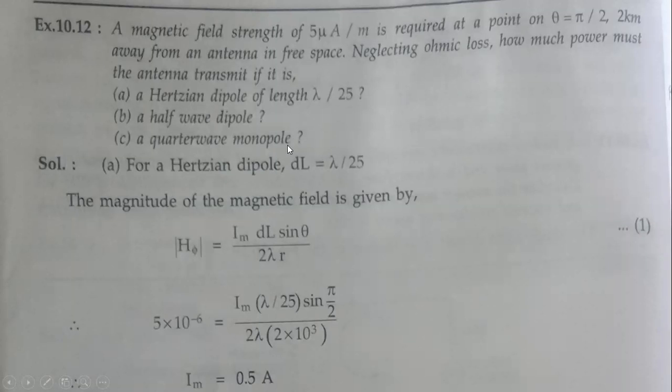So how can we start? The A part is for the Hertzian dipole, so dl is equal to lambda by 25. The magnitude of the magnetic field is given at the beginning of the question, that is 5 micro ampere per meter. As theta is given, the possibility is either the cylindrical or spherical coordinate system. You can take the spherical one, just looking at the shape of the transmitting antenna in the dipole form. So here the magnitude of that magnetic field is